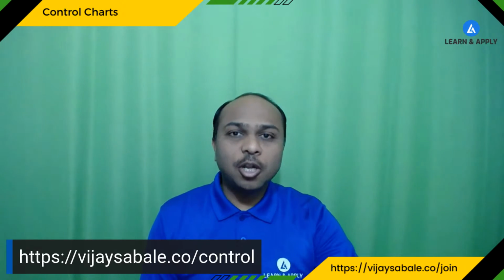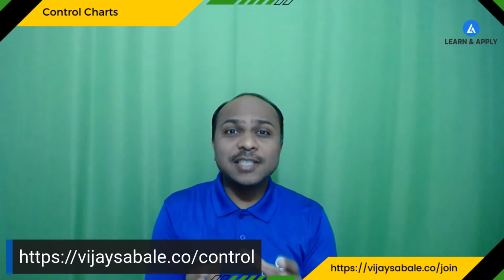Okay, so there is one comment or question. What is the subgroup size? Okay, that's a great question, Akash. Subgroup size is like that. Many times we are not collecting data as an individual unit. That means we are collecting 2 or 3 data points or 5 data points more frequently. And we are taking the average of those points and we are using that average to plot the control chart. So that is called data collected in subgroups.